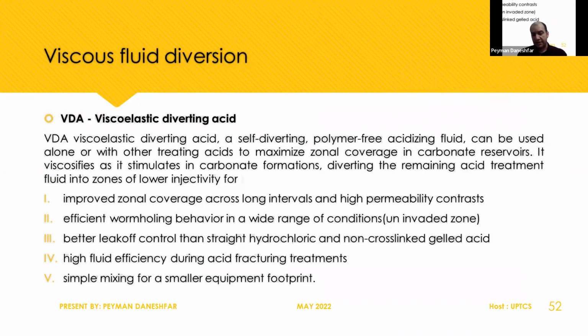The industry now uses the VDA system. VDA is a diverting acid or a self-diverting polymer-free acidizing fluid, which can be used alone or with treating acid to maximize zonal coverage in carbonate reservoirs. I told you before, if we acidize the total interval of the well, we do our best job. Okay, we do the best acidizing.